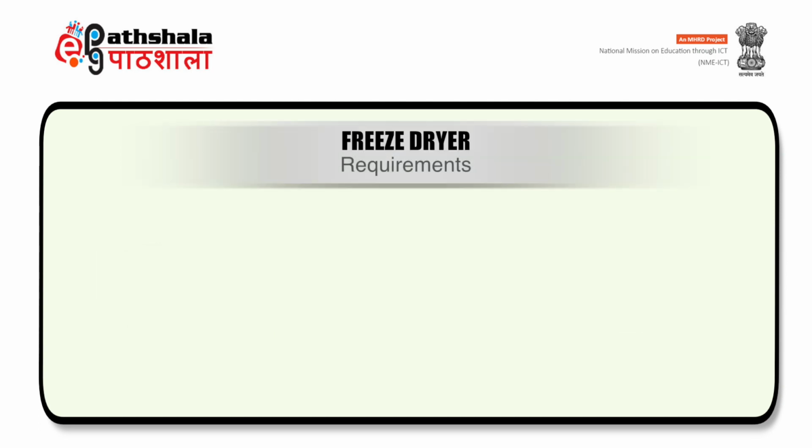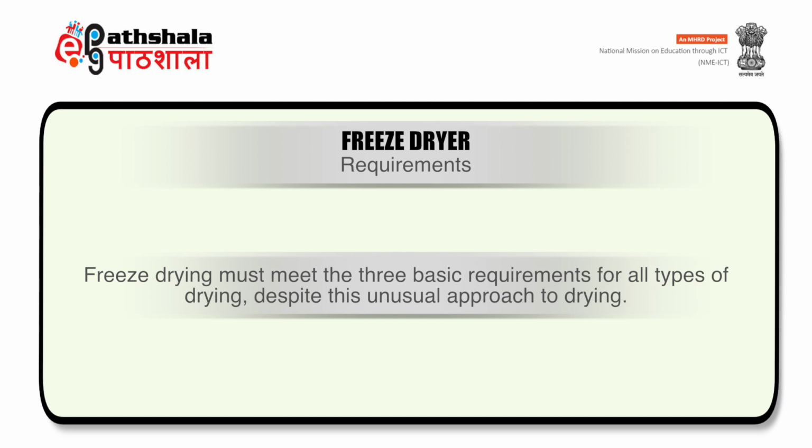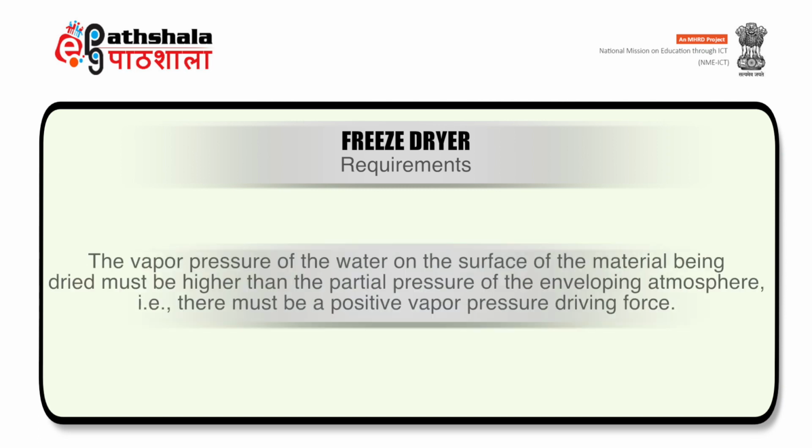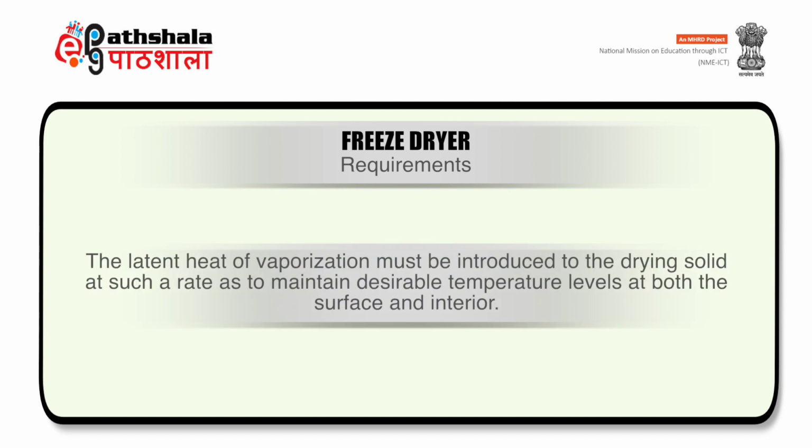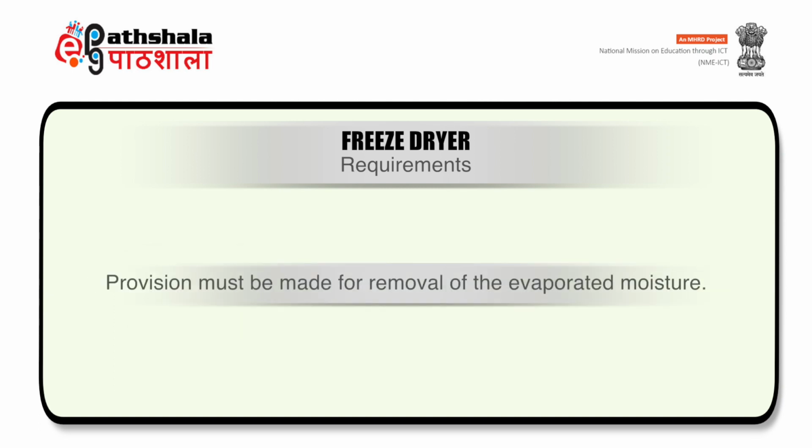Now, requirements for freeze drying. Freeze drying must meet the three basic requirements for all types of drying despite this unusual approach to drying. First, the vapor pressure of the water on the surface of the material being dried must be higher than the partial pressure of the enveloping atmosphere, that is, there must be a positive vapor pressure driving force. Second, the latent heat of vaporization must be introduced to the drying solid at such a rate as to maintain desirable temperature levels at both the surface and interior. Third, provision must be made for removal of the evaporated moisture.